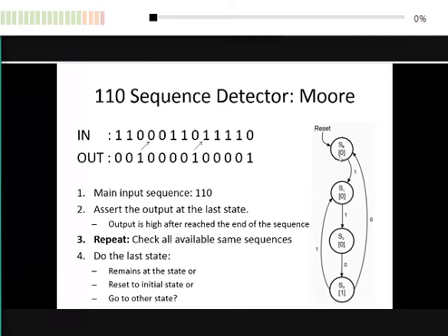Okay, now if you can do this, you already got 67% of the state diagram. That's a lot, 67%, you already got B. So now the last part is to carefully complete all the arcs. Because you see at S0, the output arc is not complete. You only have an output arc when it is 1. But what happens when the output arc is 0?